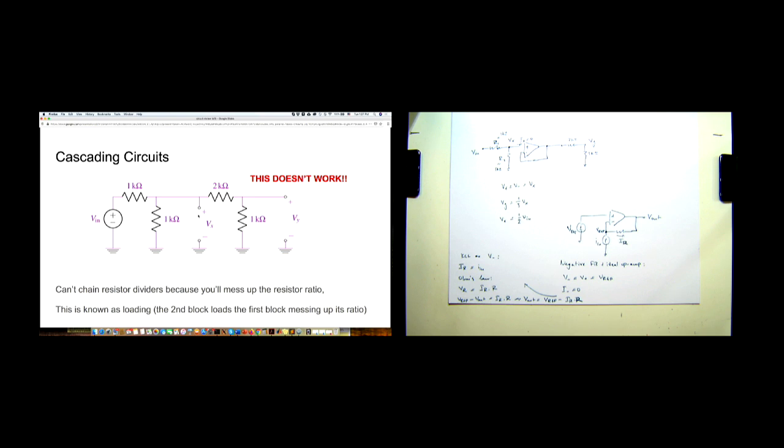So because we directly add it there, we say that it loads that node. It changes the effective resistance seen from that load to ground, and hence it changes the divider ratios. And load, you're saying it adds current to the... So yeah, essentially you draw some more current through this branch, and because you draw some more current, you mess up this division ratio. Does that make sense?